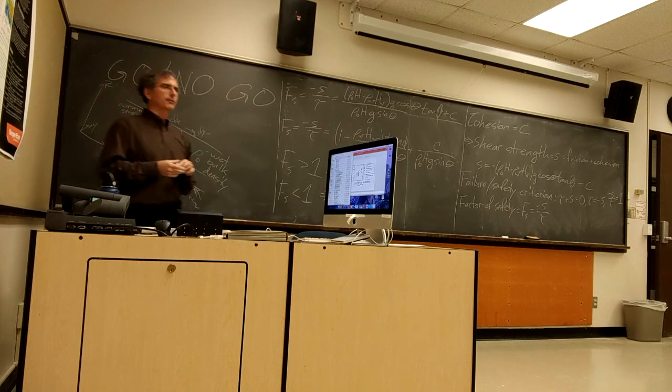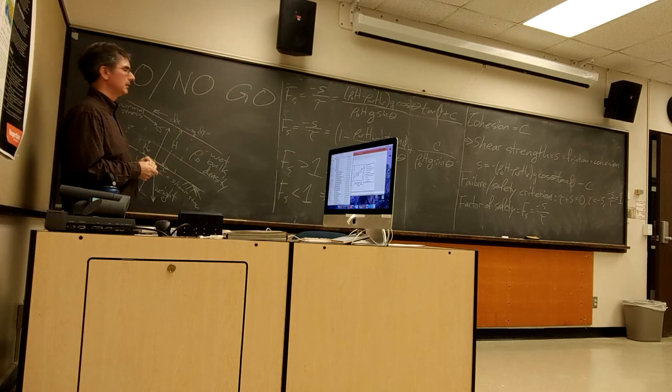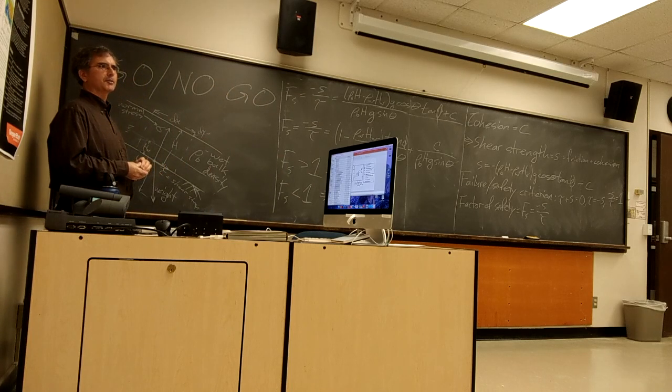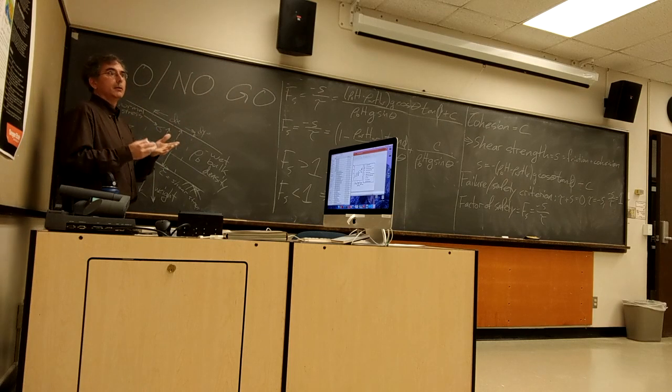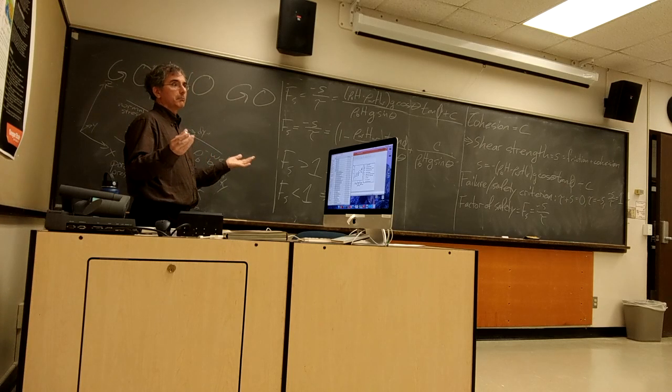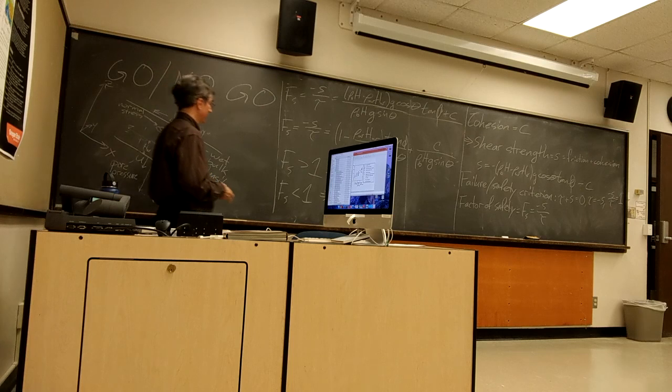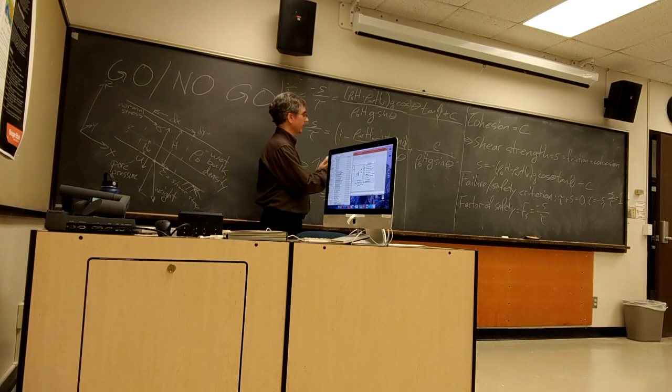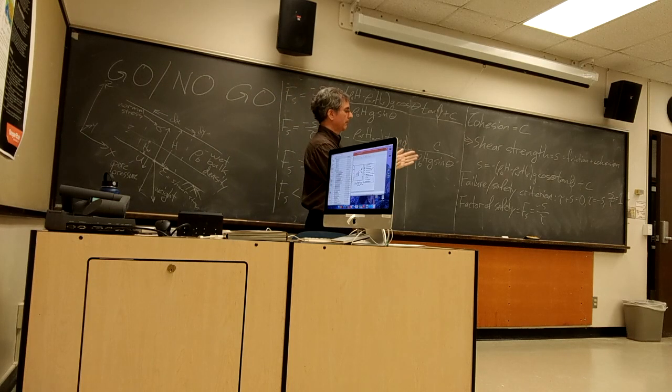So 37 degrees for the friction angle, 41 degrees for the actual slope angle in a lot of parts of the coast range. So again, cohesion, cohesion, cohesion. It doesn't fail when it's dry. It also doesn't fail when it gets pretty wet. So cohesion is pretty big, and we will continue with that next time.